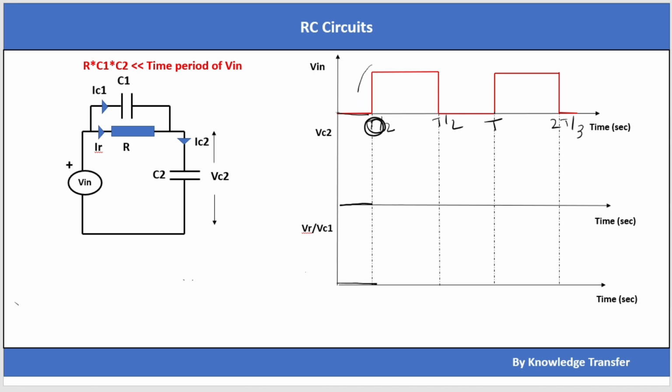You can see at t equal to 0, the high frequency signals are being applied to both capacitors C1 and C2. Okay, so if I draw an equivalent circuit here, this will become like this. So this will be one resistor, one capacitor. Because of high frequency signals, it will get short circuited, and in the same way the capacitor C1 also will get short circuited.